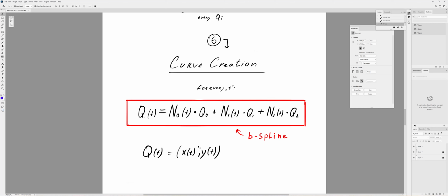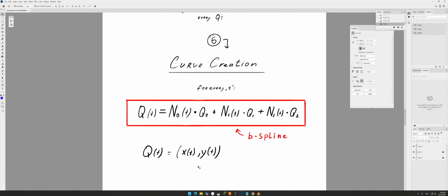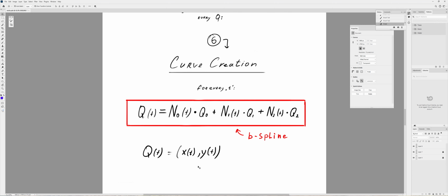So we take all the big data which we have and eventually plug it all together. Everything is tied to the basis function, the t parameter, and our control vertex coordinates, because without coordinates, we can't construct other points. That's where the magic happens. So these q(t), or x and y coordinates, will be calculated using this formula for every given parameter. And that's how we get our points, and that's how Alias interpolates and gives you this beautiful NURBS curve, in our case, a parabola.